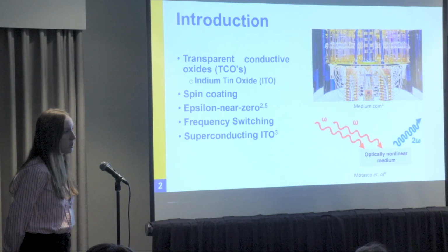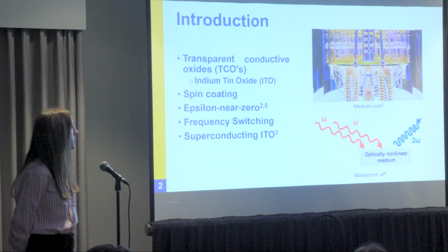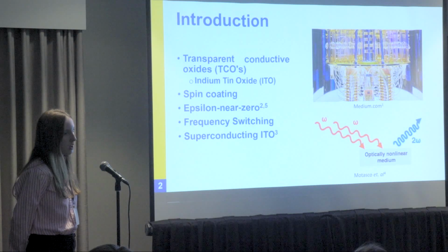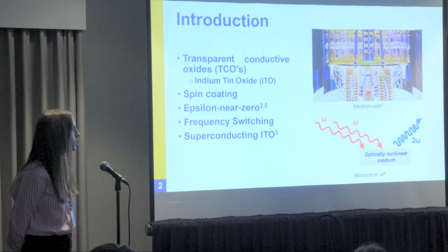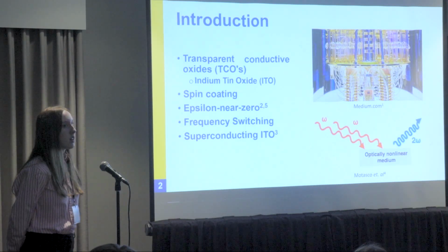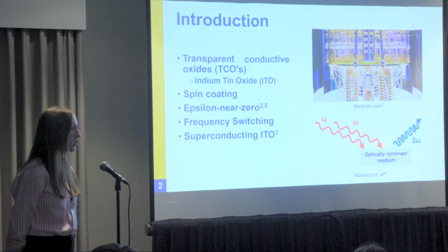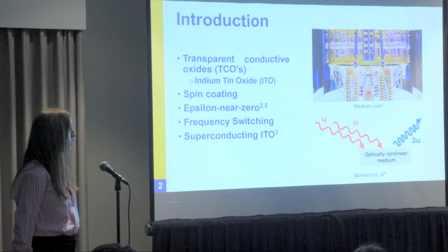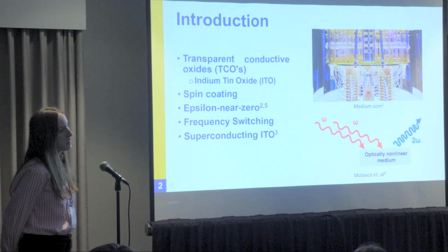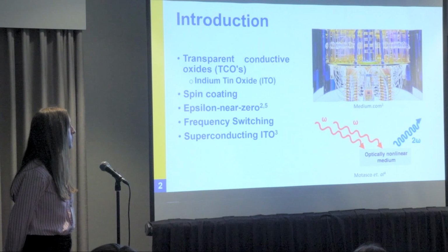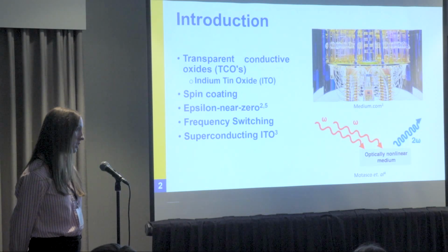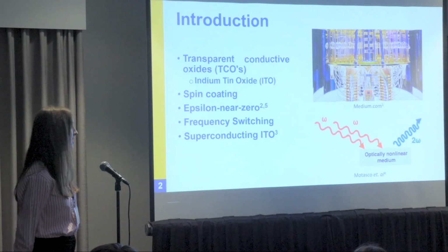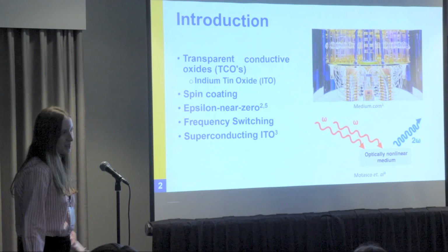We made our indium tin oxide thin films using spin coating deposition, which is an alternative to traditional commercialized thin film deposition techniques, such as chemical vapor deposition and magnetron sputtering, which require large facilities and high levels of technical training for use. Spin coating can be done benchtop, which reduces the facilities needed for deposition and requires very little technical expertise, which is why we were able to use it as undergraduates.